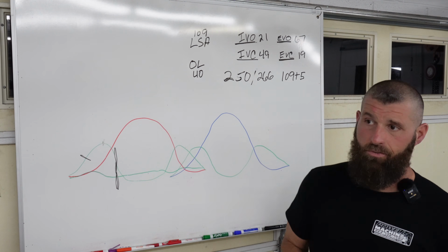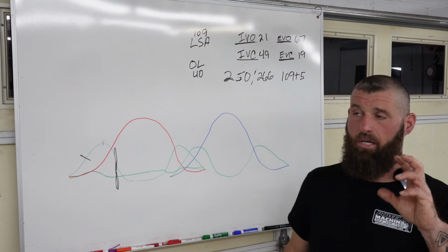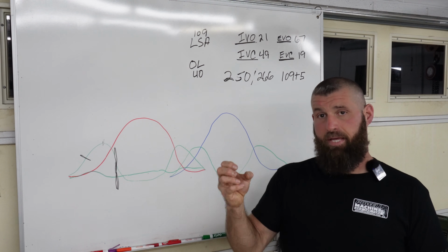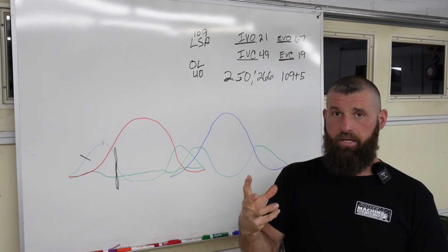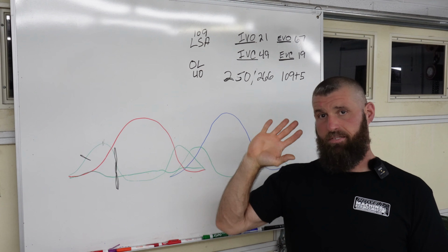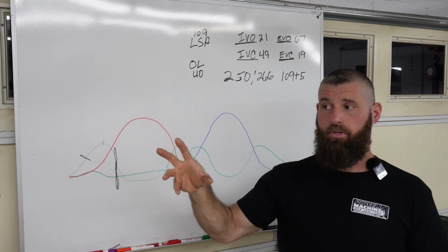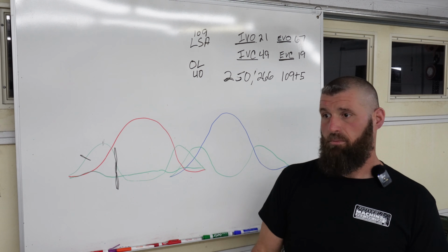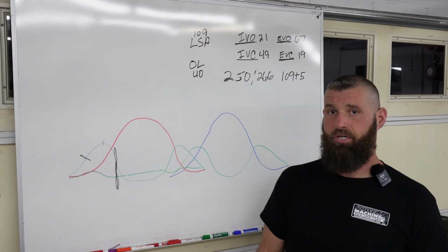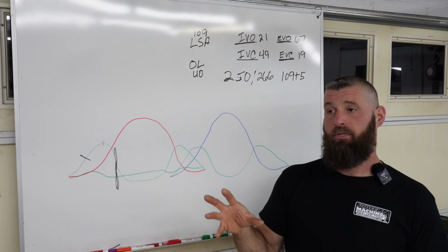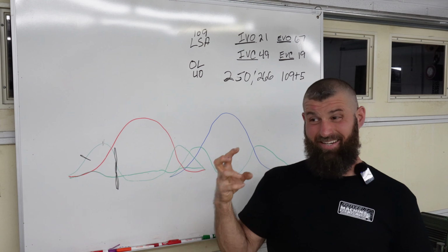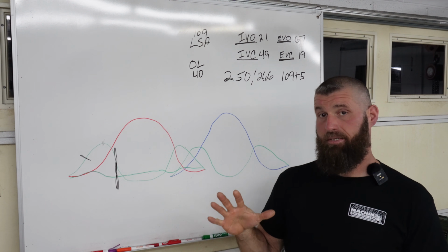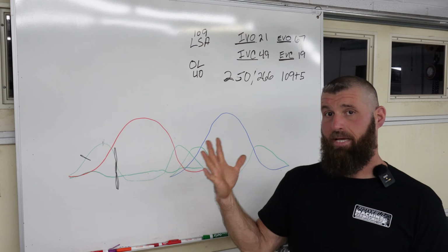Man, we're running, a lot of them's on alcohol, methanol, whatever you want to call it. And the gas is just thick and heavy, and it takes a lot of extra work to get it out. So a lot of those motors, we're running, man, 25 degrees of split. Nitrous is like that. Nitrous is heavy. We're running tons and tons of split in the exhaust to make that work out.